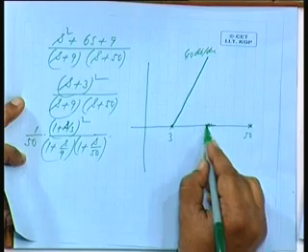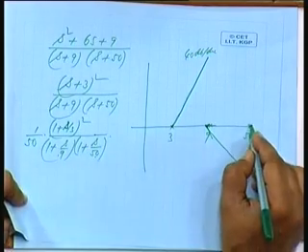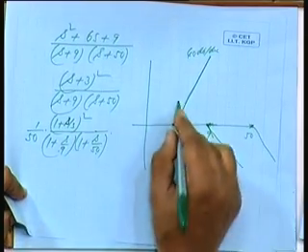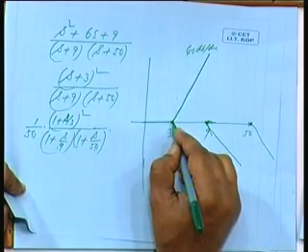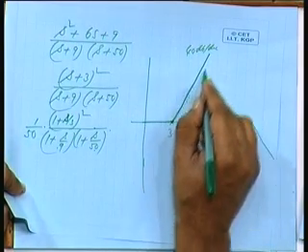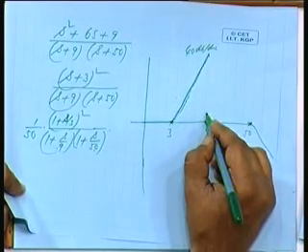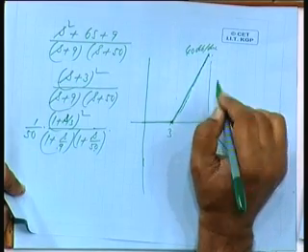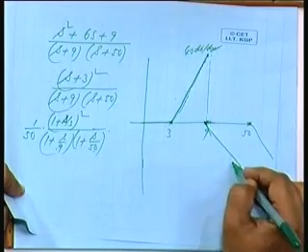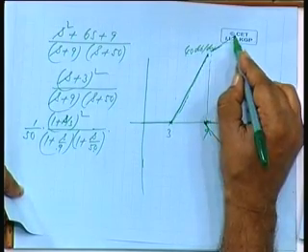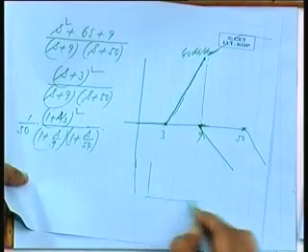It will be minus 20 dB per decade, and then again at 50, minus 20 dB per decade. So, what is the resultant of these three? The resultant, if I am permitted to draw by a dotted line like this, will be this line, and then at 9, it will be plus 20 dB per decade, it will go on like this, and at 50 it will become horizontal.